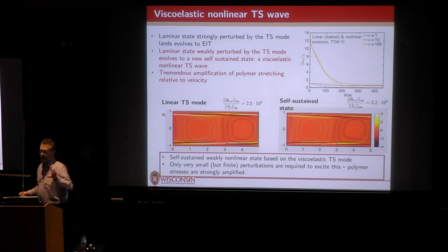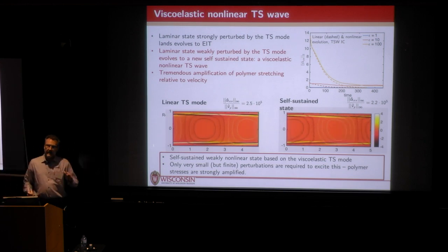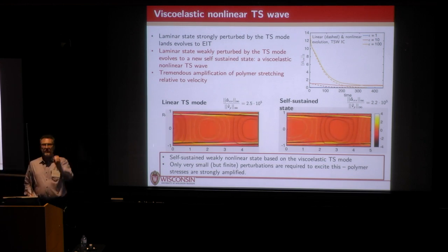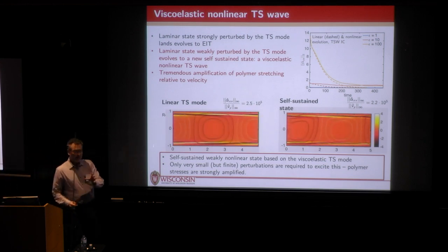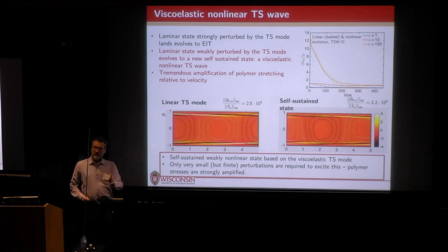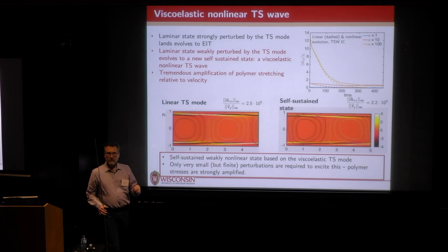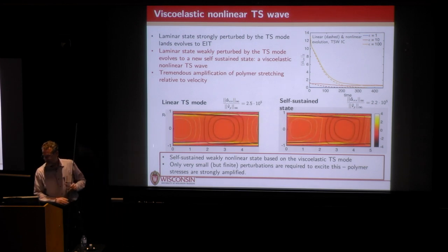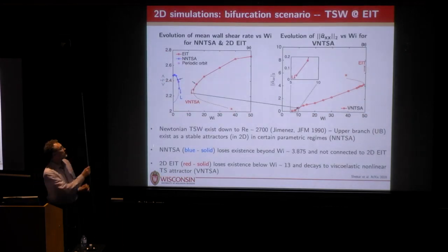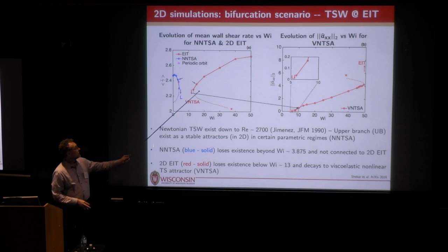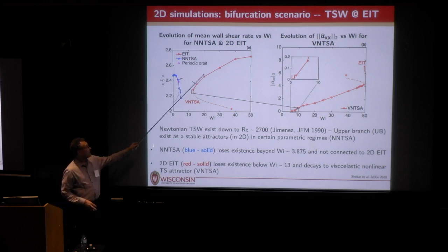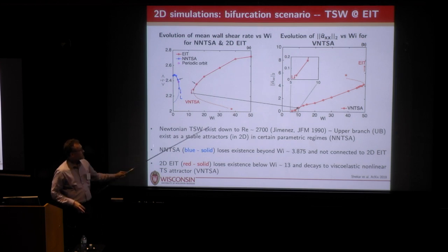And what's interesting is that once the Weissenberg number is around 4, that ratio really ramps up, and a Weissenberg number of 6 is where this nonlinear traveling wave solution comes into existence. All right, so just coming back to here. The point is there are 2 branches of nonlinear Tollmien-Schlichting waves. There's a Newtonian branch and an elastic branch that kind of goes like this.